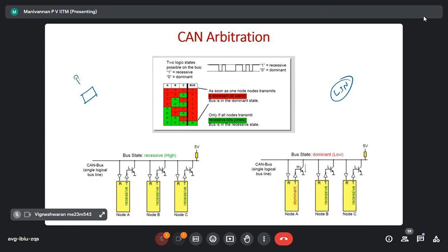These are called body electronics. In body electronics, there is one ECU. On the door there's only a micro switch. There's a motor which is going to move the mirror up and down, controlled by the microcontroller, whether by automatic or manual switch.